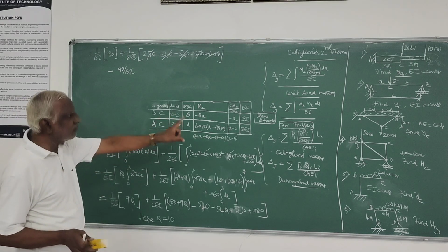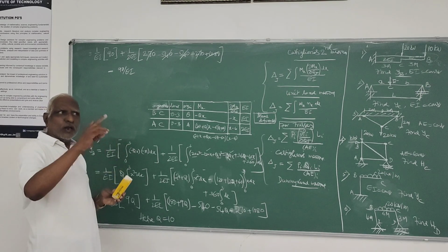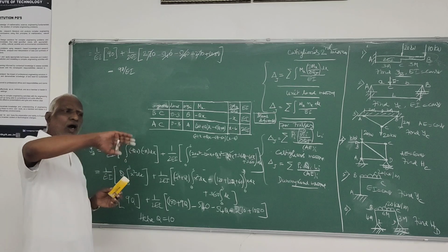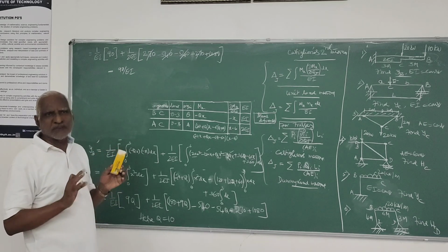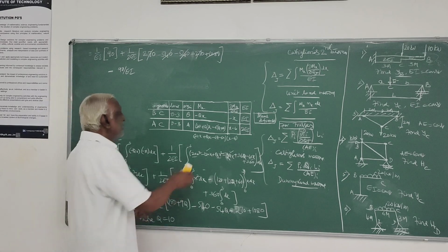You always apply a load along that coordinate. That load may be a vertical load if deflection is required, or it may be a moment if slope is required. That's all. Now, unit load.